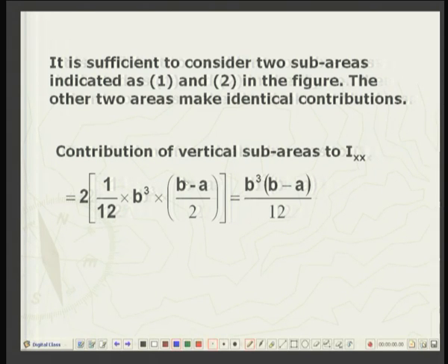Okay. For this calculation, you can find the second moment of area of a rectangular body from handbooks, or you can easily integrate it. You will find that if you have a rectangle of width b and depth h, then it is bh cubed, that is width into depth cubed, divided by 12.